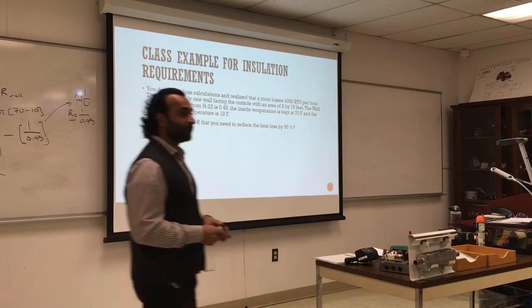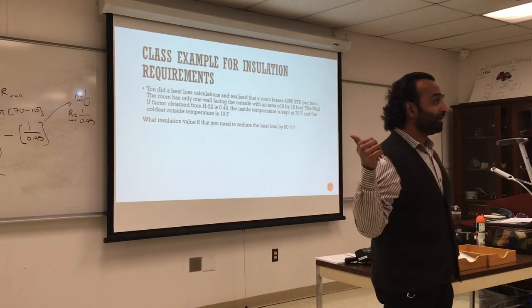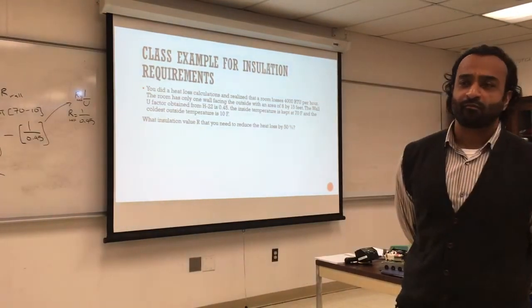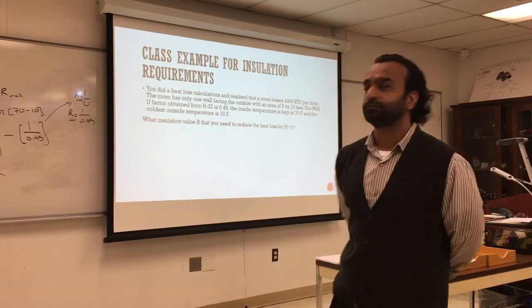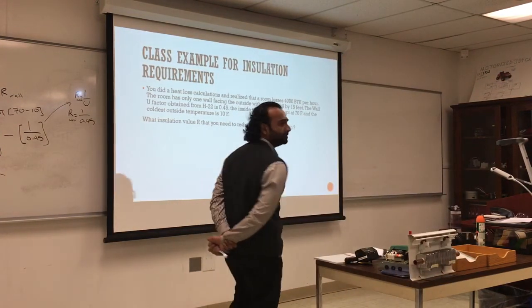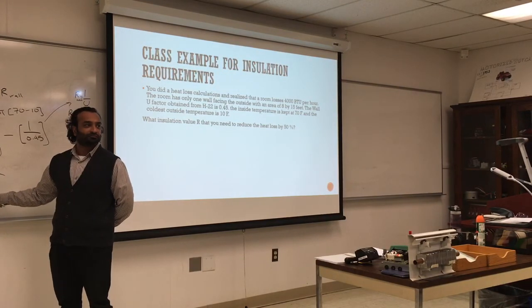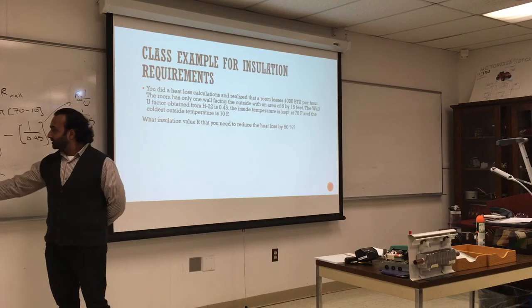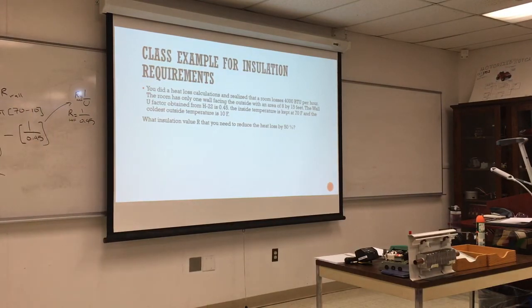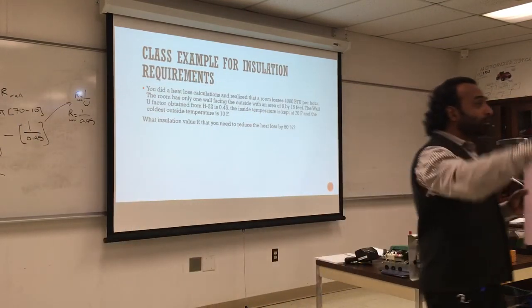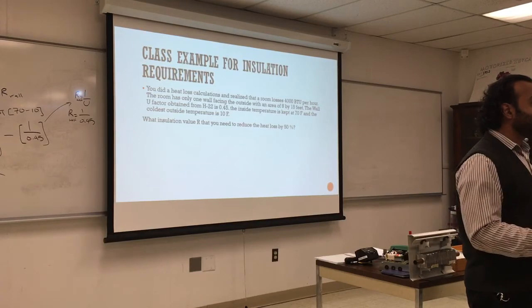Any question? Jason, you got it? If you use the other equation, oh, that's for infiltration, never mind. What was the last number you did? Why did we cut 3.6 by 50%? Just 2.22 minus 2.2. What is the R value you need to add to that wall to reduce the heat loss by 50%? So you're going to cover the wall with insulation that has an R value of at least 1.5.